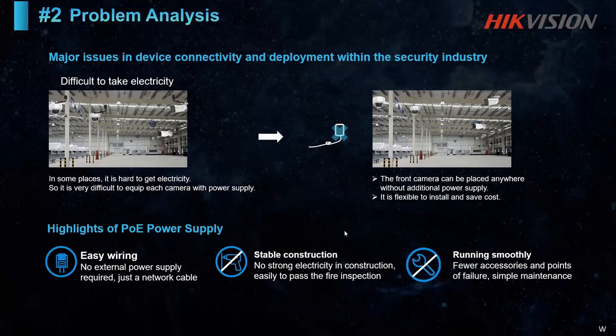Actually, this is not directly related to the switch field, but more to the CCTV surveillance side. When you are using an analog camera, normally you have to use two separate cables, one cable to transmit data and another cable to transmit power. But if you are using a network camera with the PoE function, you can transmit both data and power on the same cable. Some switches have this PoE functionality, which means power over Ethernet. Because of that, the wiring would be easy.